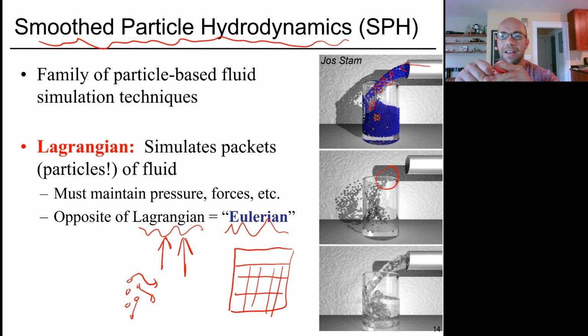So rather than following particles around as they interact and swirl in this big bucket of water, I'm going to think of myself like a little barnacle and just counting the number of particles that move past. Maybe if I'm representing the velocity field of the water, then I'll do that at a fixed XYZ location rather than one that's moving along with the particles. This corresponds to something we'll call Eulerian physics.